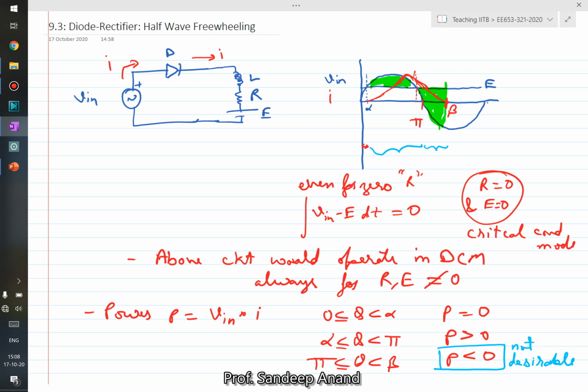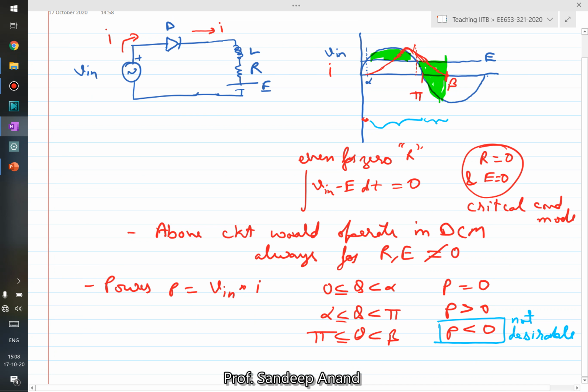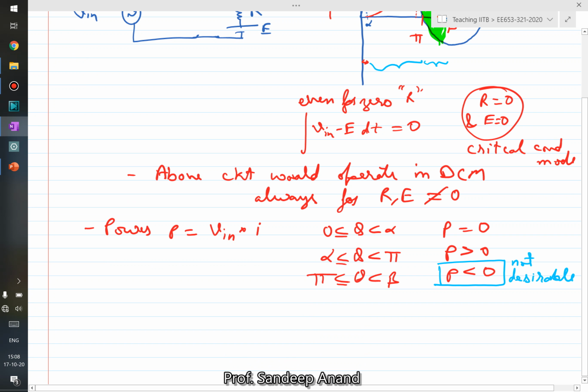That is practically when we talk about AC systems and linear AC systems, wherein you do not have diodes, which is a non-linear element, you have only voltage sources and resistance and inductors and so on. You would like your load to operate at unity power factor. What does unity power factor mean? Unity power factor means that your voltage as well as current, both should be in phase. What does that mean? That if you multiply the instantaneous power, it would always be positive.